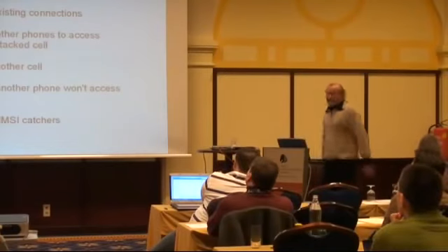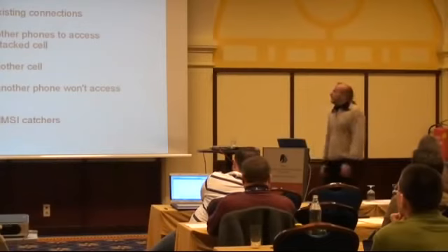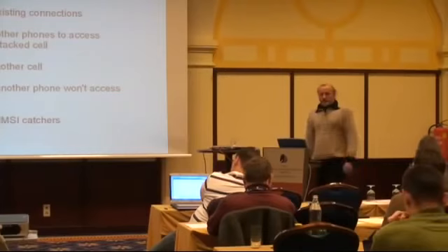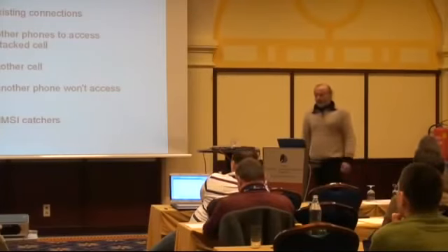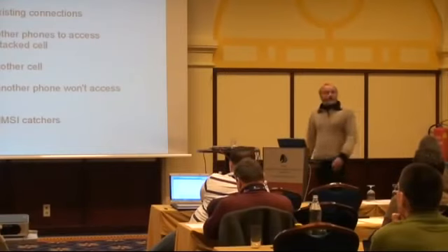When you do this, you first of all jam the signal of other phones. If you are very close to your BTS and you send a strong signal, the other phones don't have a chance to come through. You have the strongest signal, you win. The second effect is, of course, resource allocation. Those channels are exhausted rather quickly.